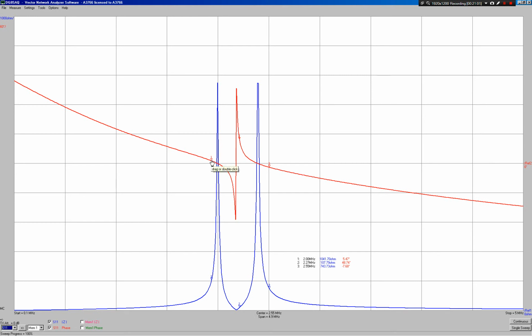We see again that essentially the upper and the lower frequencies are collapsing onto each other. In other words, the effect from the primary and the effect from the secondary, they're not interacting so much. The coupling coefficient's gone down, and therefore they are essentially becoming more independent circuits, and therefore not influencing each other to the same degree.